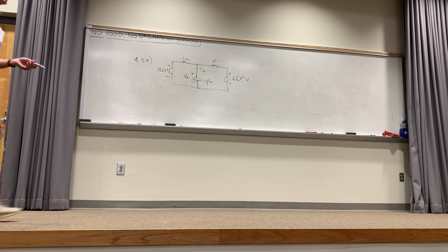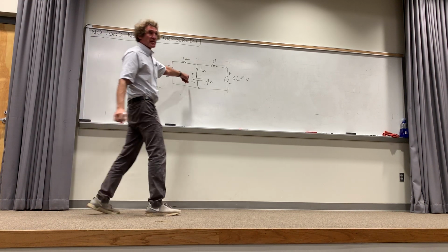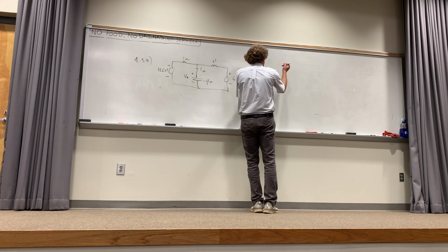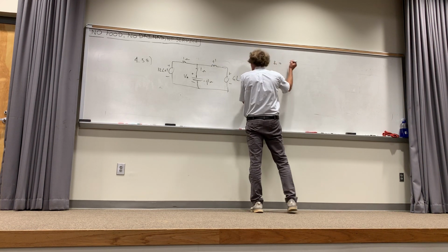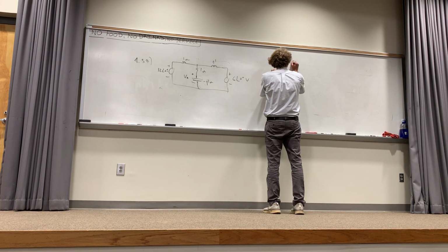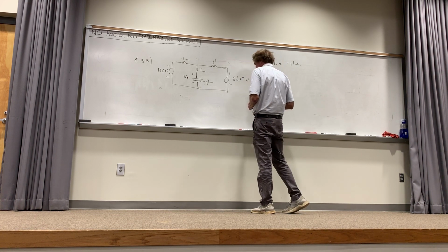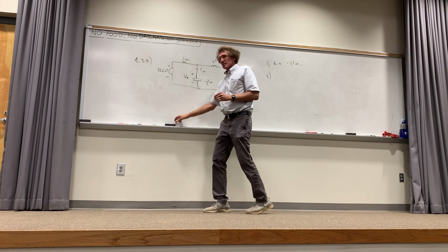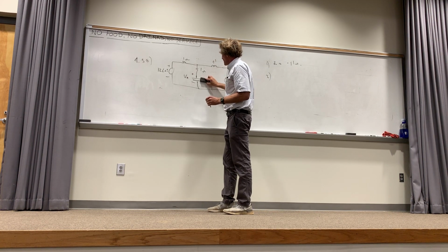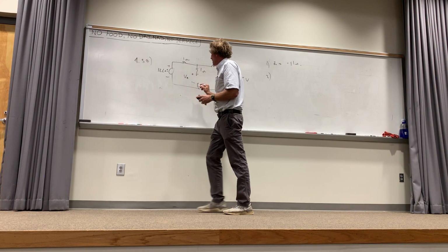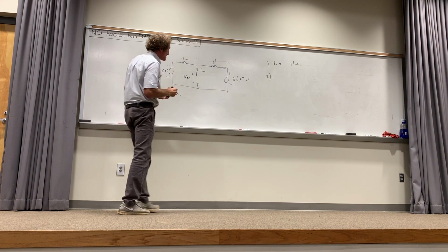First thing is what? You locate the load, right? My load, call it Z load, is equal to minus j1 ohm. That's 1. Number 2, you remove it. So the second thing I do is remove it. And then I want the open circuit voltage there.